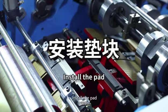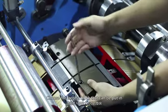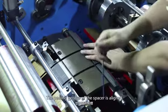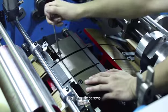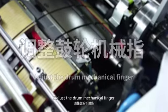Install the pad. Choose the largest block that can be put in. Install cushion blocks before and after the second fixture. The peeling groove of the spacer is aligned with the peeling groove of the drum wheel. Tighten the screws. Adjust the drum mechanical finger.